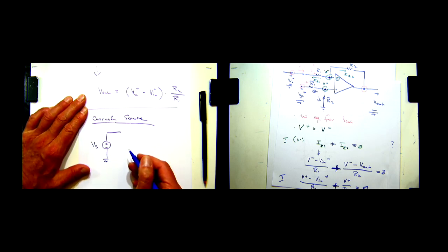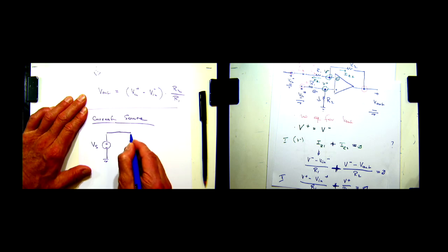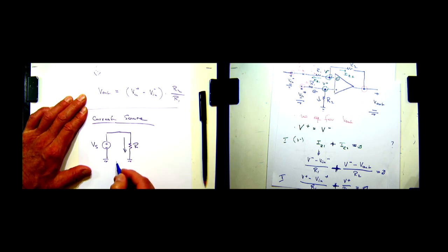Now we want the current. Well, what element could we use to generate a current? Well, a resistor, R. In fact, what is the current? Well, the current IR is going to be equal to Vs over R. And it's even constant as long as we don't change the value of R, that current is constant. So it is actually easy to generate a current IR that is constant. There's just one little rub in here. What's the rub?